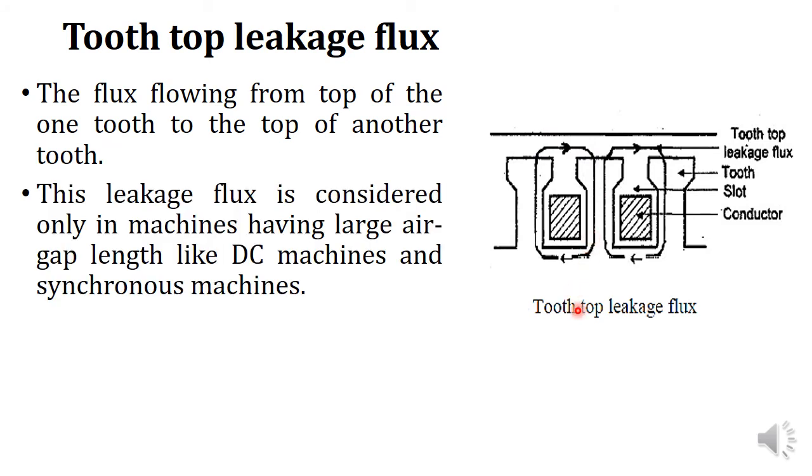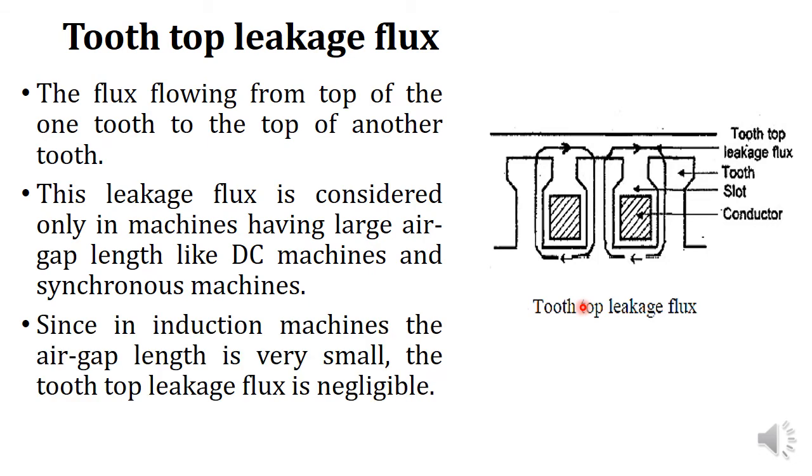And this leakage flux is considered only in machines having large air gap length, like DC machines and synchronous machines. But in the case of induction machines, this air gap will be very small. So this kind of tooth-top leakage flux can be neglected in the case of induction machines.